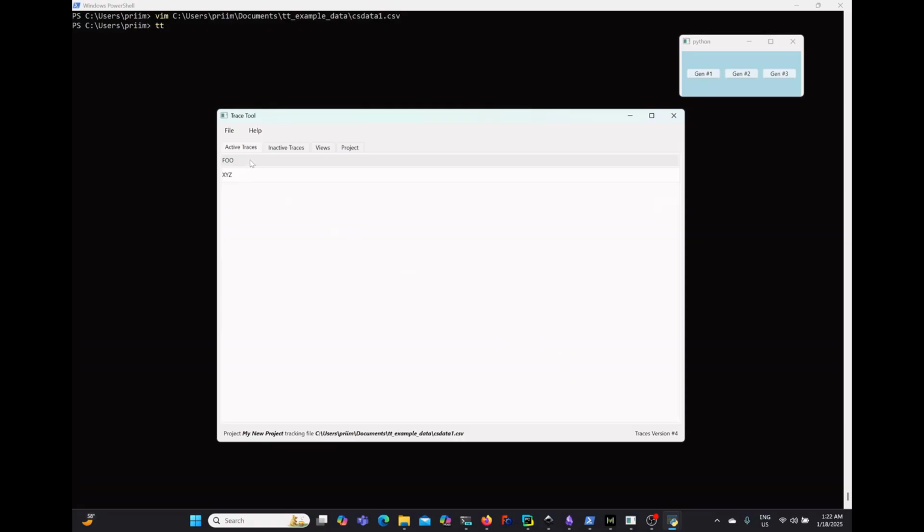Now, how can we access the versions? A typical behavior is that you made some change. You run ChipScope capture. You didn't like the results. You're gonna change some settings in the FPGA, or you're gonna change your chip, or you're gonna change the model itself. You're gonna change the netlist and run the capture again. So you probably want to see immediately before and after what the changes were.